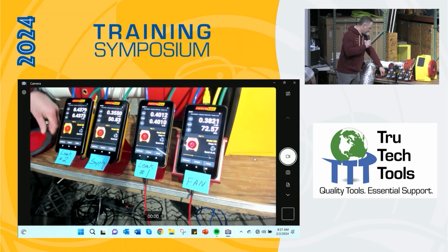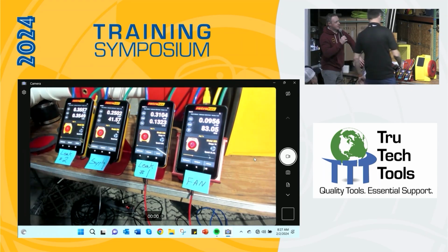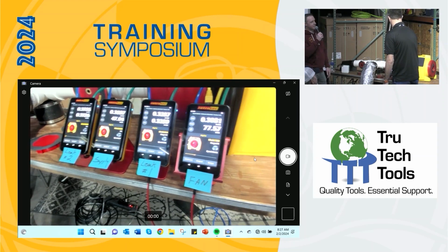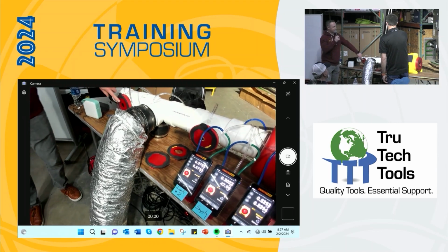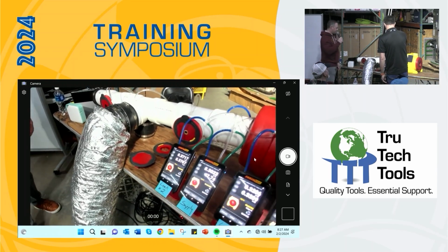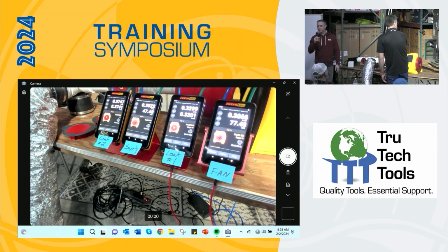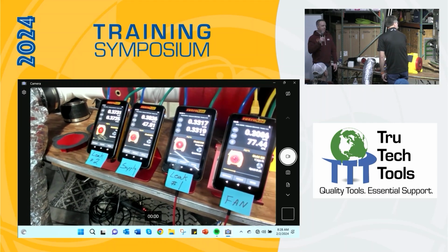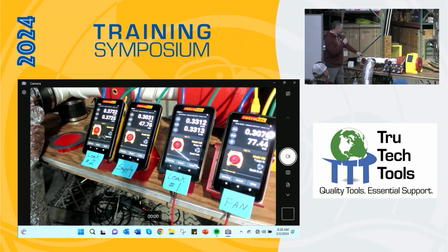Obviously, if I make this a little more dramatic and put a larger hole downstream, let everything settle back out, then, yeah, there we go. Thanks, Eric. Then, yeah, it's just going to drop more. So as leakage increases, the static pressure goes down. So sometimes maybe low static pressure can be an indicator of a leaky system. It's not always a good thing, especially if we're going to go in and change it later and that static pressure comes back up.